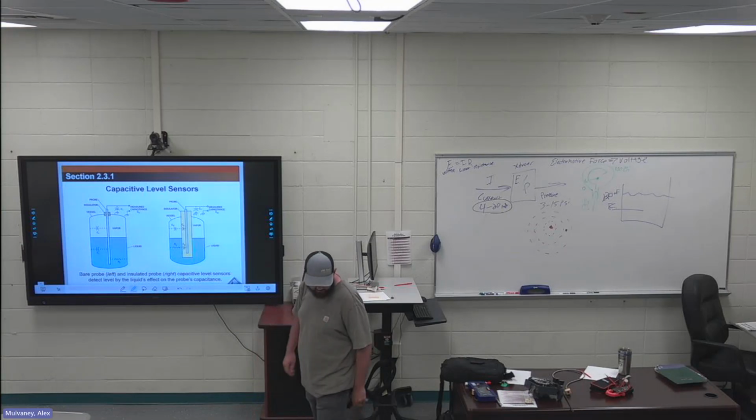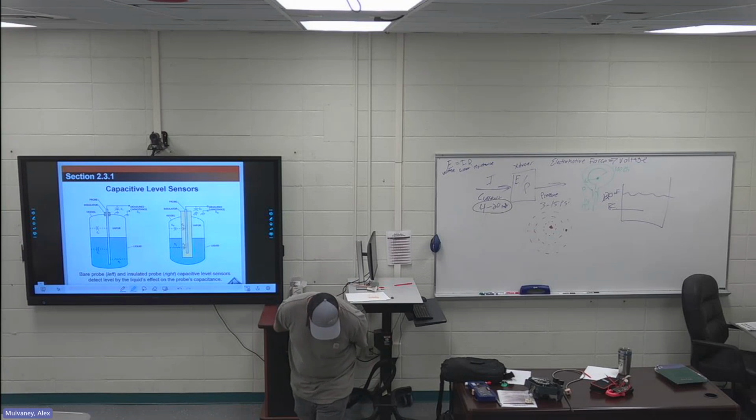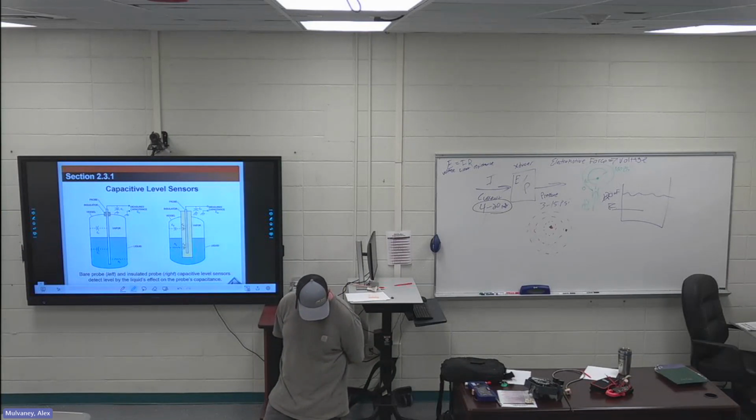Flip over to page 26. The third paragraph on page 26. Right in the middle of that paragraph, I have a highlight. As previously shown in table 5, the dielectric constant of water varies greatly with temperature. This can be compensated for through the use of an RTD or thermistor as another input to the measurement system. Both of these devices react linearly to changes in temperature.